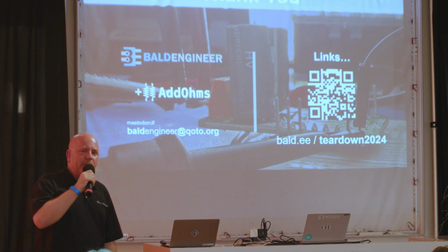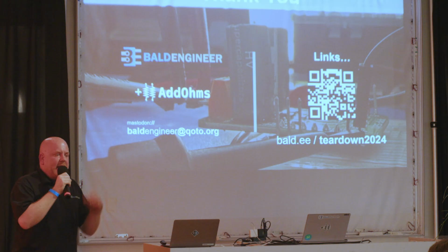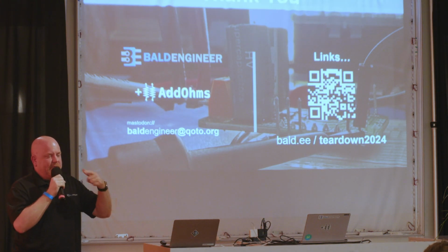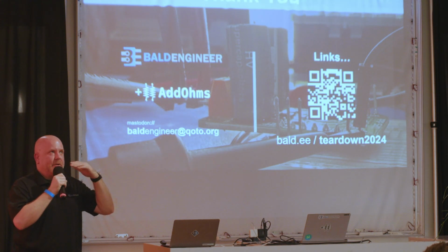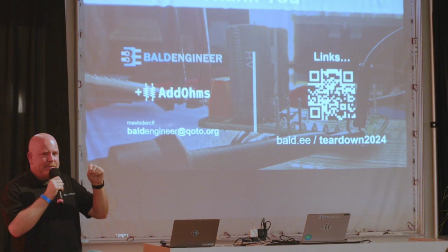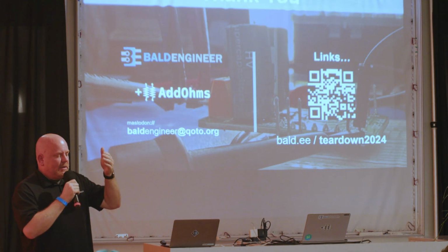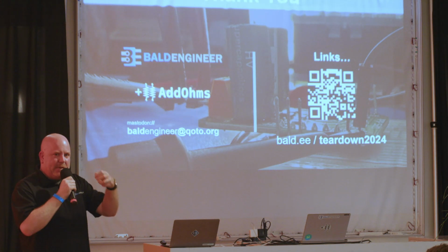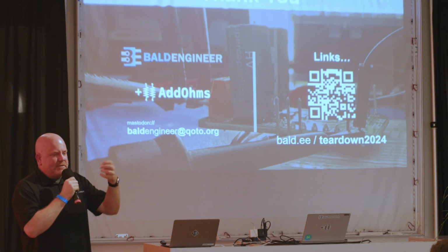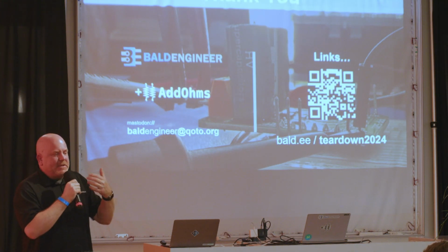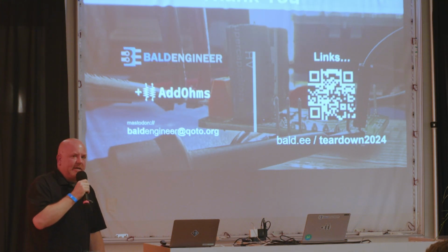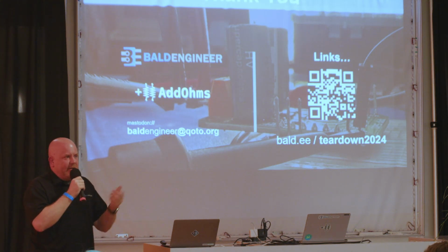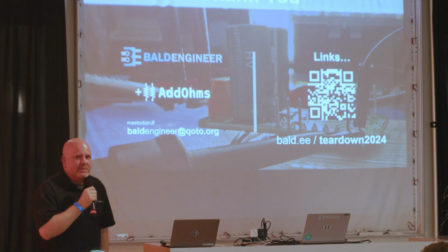What caps have the safest failure modes? Film caps. You think of them as layers of saran wrap that have metal vapor deposited on top of it. So it's a really, really thin metallization. Anytime there's damage in the dielectric, it creates a short, and that short actually causes the plastic to melt. There's so much more plastic than metal that it effectively disconnects the fault site. And so they actually fail open. It is extremely difficult to get a film cap to fail short, other than when you put a nail through it, then it's really easy.